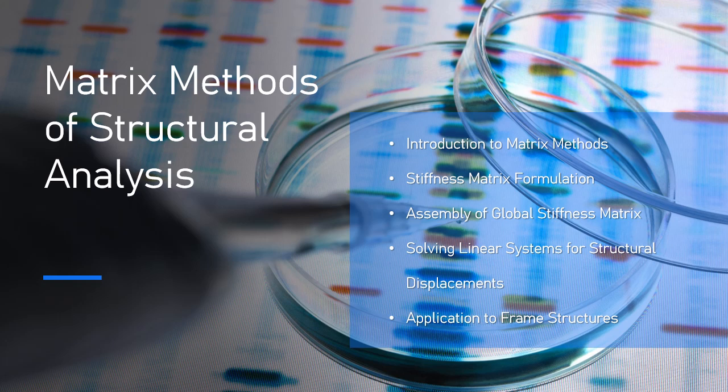2. Formulate local stiffness matrices. For each element, truss, beam, frame, etc., a local stiffness matrix is derived that relates the forces and displacements for that specific element.